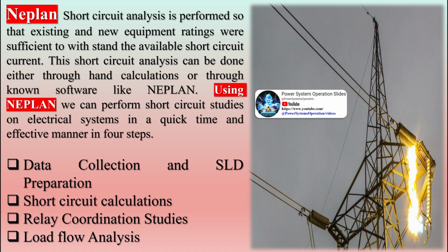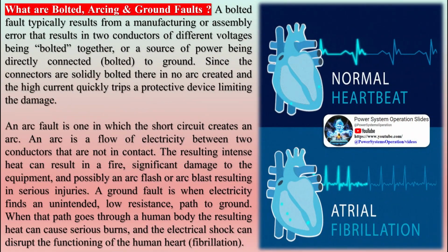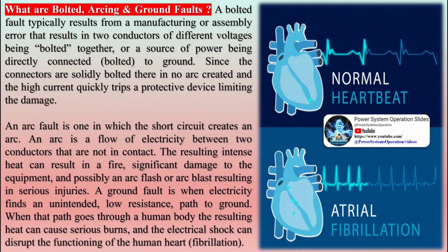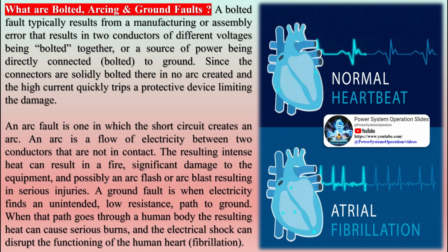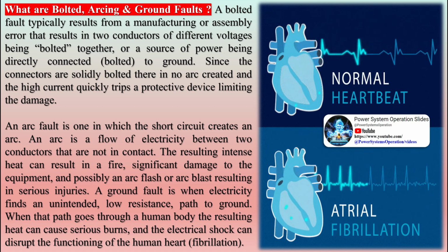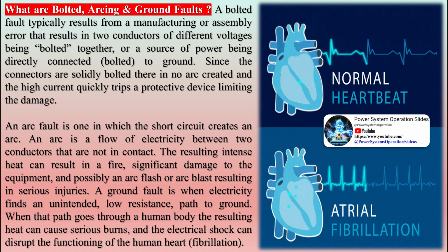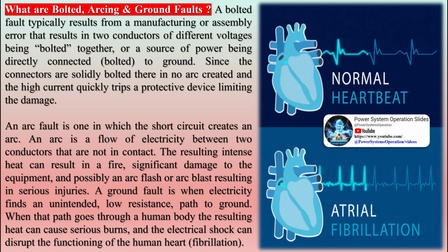What are symmetrical and asymmetrical currents? A polyphase system may experience either a symmetrical or an asymmetrical fault. A symmetrical fault current is one that affects all phases equally. If just some of the phases are affected, or the phases are affected unequally, then the fault current is asymmetrical.